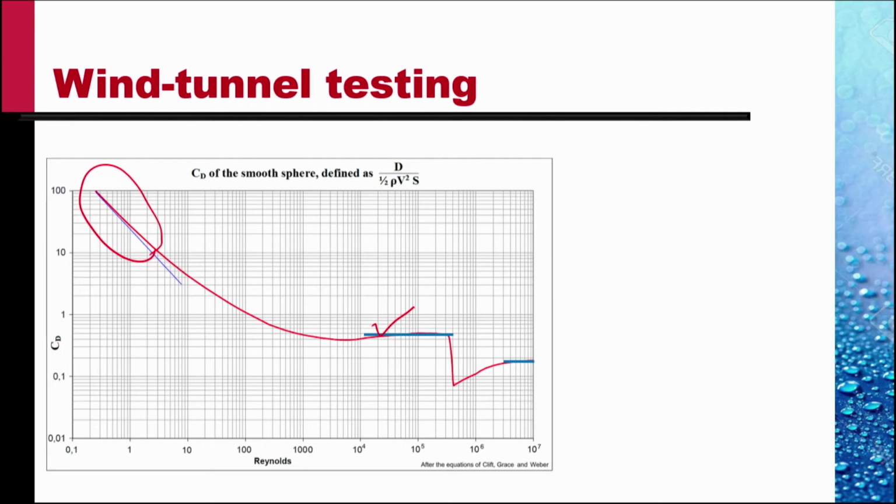Then, again at a much larger value. We had seen in a fluid dynamics course that the first region represents the region of laminar separation around the smooth cylinder. And the second is when the boundary layer is turbulent. So there's turbulent separation. But the drag coefficient is constant.